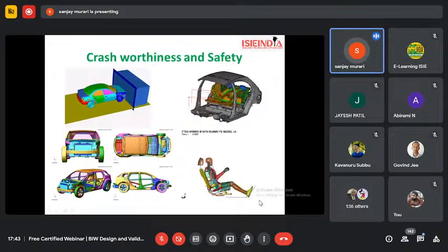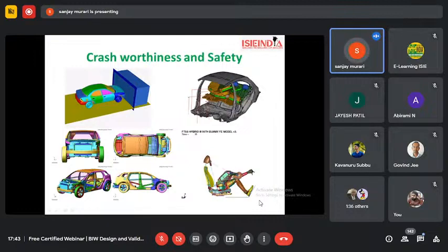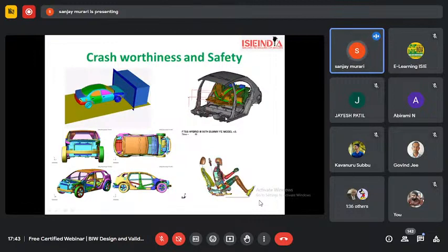That is the reason if you see this gray colored BIW part, there are many beads on it, or some long imprints. Those beads do the work of stiffness, because here we are changing the geometry of the component and trying to achieve the desired stiffness.